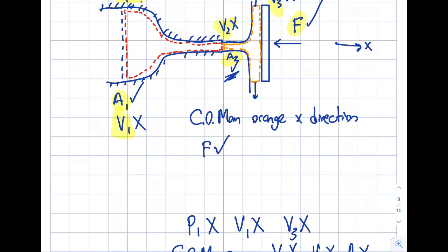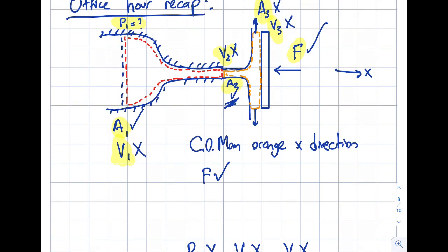Okay, right now as you see there's nothing contained inside of a pipe. I don't have to worry about the pressure forces, so that's good. V3 and A3 are unknown. However, when I write my conservation of momentum in the x direction, they are going to be perpendicular. The velocity 3 will be perpendicular, so they will not be playing a role there. And you see here that the only unknown that I get is V2.